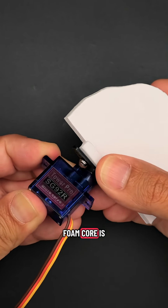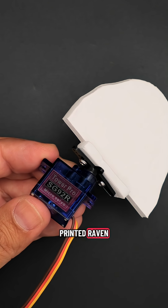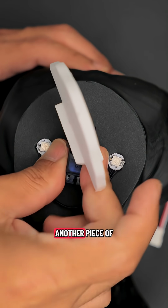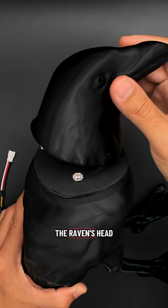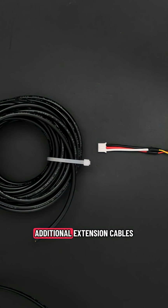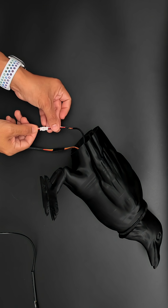A piece of foam core is secured to a servo horn that press-fits into the head of the 3D printed Raven. An additional set of neopixels are wired together and fitted onto another piece of foam core with a cutout to secure the servo motor. The Raven's head is then press-fitted onto the piece of foam core. Additional extension cables are used for the servo motor and neopixels.